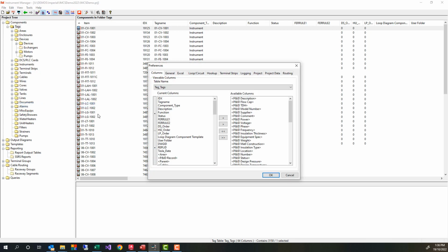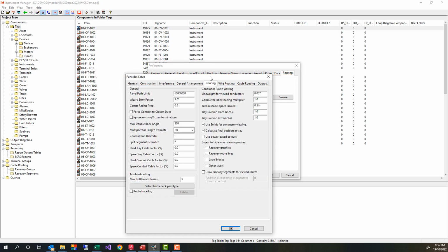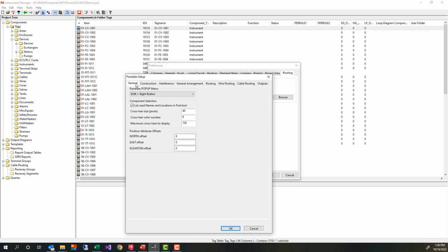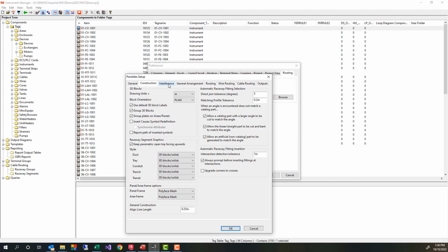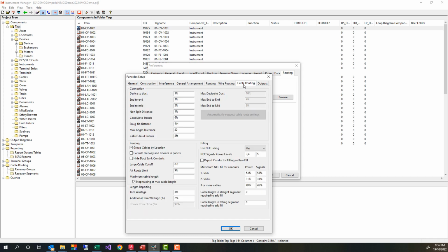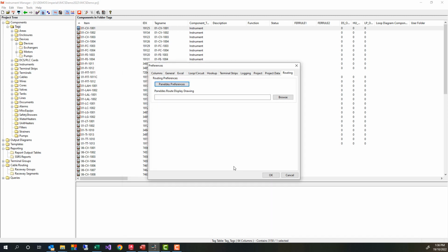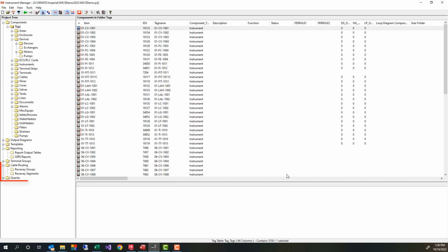It enables a user to place intelligent tray, conduits, etc. into a DWG-based 3D model and then calculate cable lengths and cable tray fills, etc. Elementaries preferences are accessible from the Instrument Manager Preferences interface. Elementaries Raceway 3D models are included directly in the Instrument Manager project. Components will appear in the folders such as motors and cables. Raceway, such as conduit and tray, will appear in the folders underneath the cable routing branch in the Instrument Manager tree.